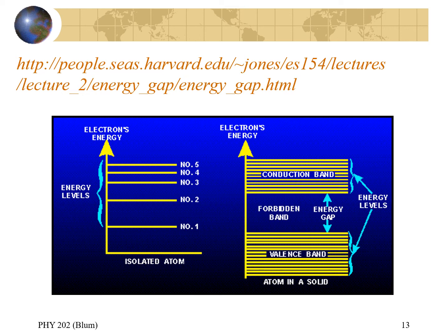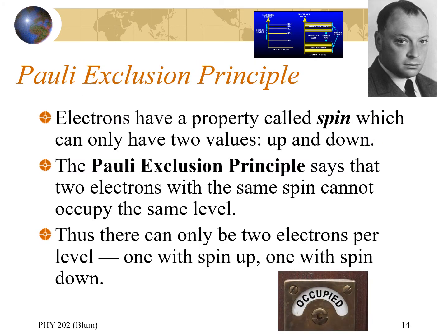These are the gaps. And just like in the atom, not all the levels were full of electrons, the same thing is true over in the band picture. We are going to have some of the bands full or half full or all the way full, but not all the bands full. And this is going to be important in our consideration of what makes a semiconductor. With both our isolated atom as well as with our solids with their bands and gaps, what's important in terms of levels or bands is whether or not the levels in them are occupied. Are there electrons there or not?